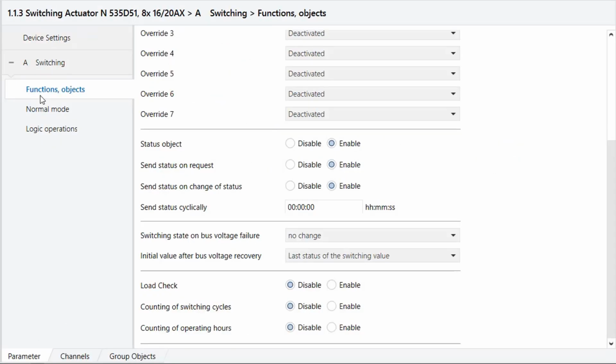The additional monitoring of the load current allows for identifying changes in the load characteristic per channel. With this function, building installations are monitored efficiently and predictively maintained by presenting failure of an operating resource, outage of a local circuit, or a contact failure.